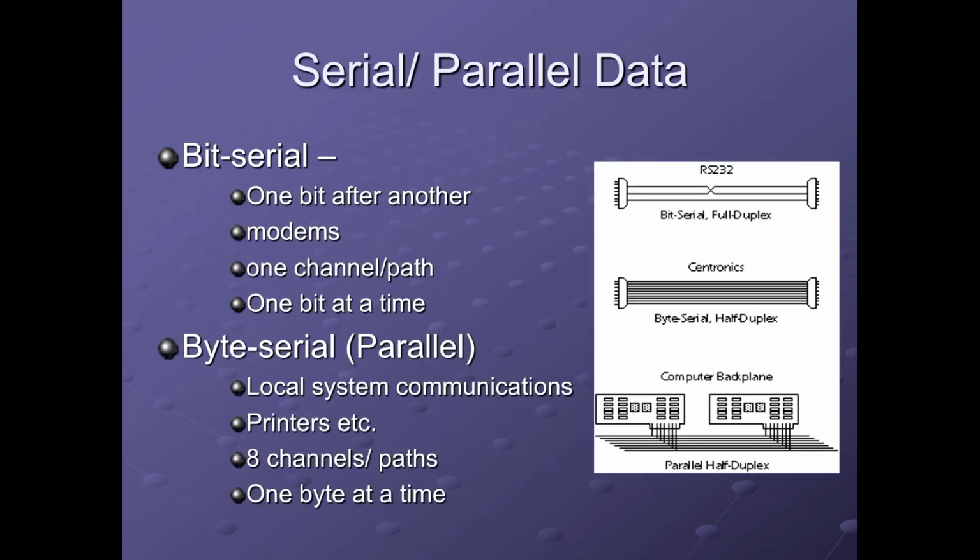So notice how both these terms have the name serial in them, but if you look closer, you can see that the second one is not bit serial, it's byte serial. And byte serial is just another way of actually referring to parallel. So if we look at the first one, the bit serial, the example of a bit serial cable we've got here is an RS-232 full duplex connection. It means that over time, your ones and zeros would be transmitted or streamed down one of the data lines, and each one of the bits is read one at a time as it's received at the other end.